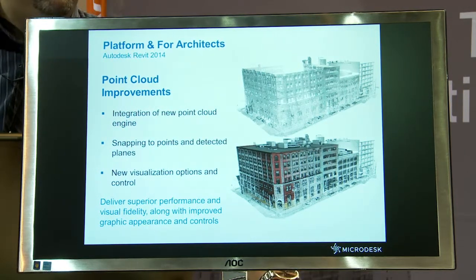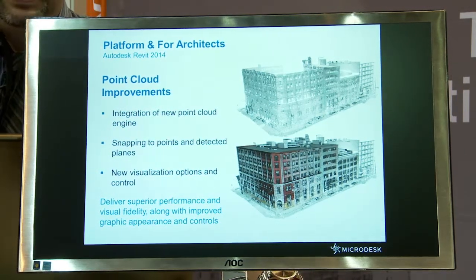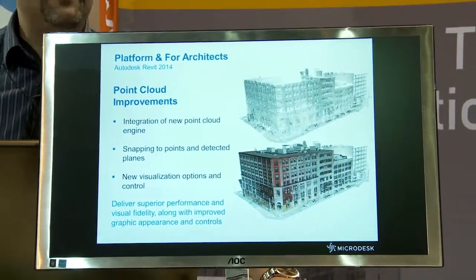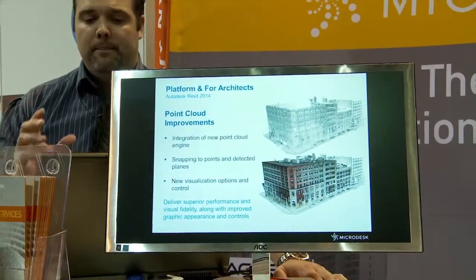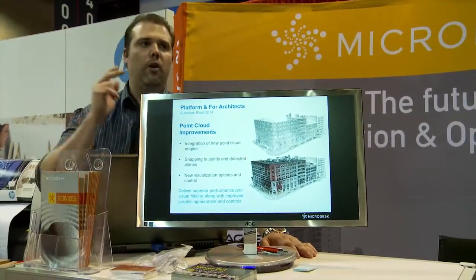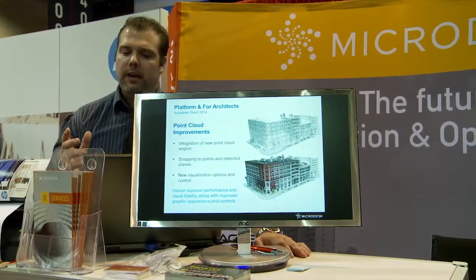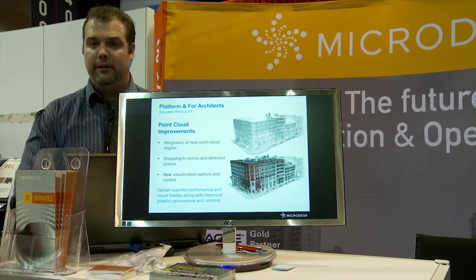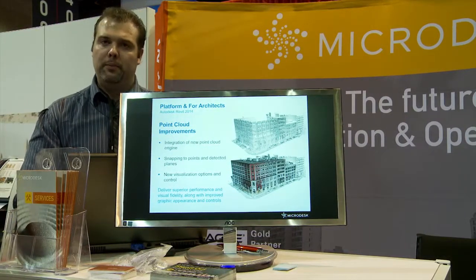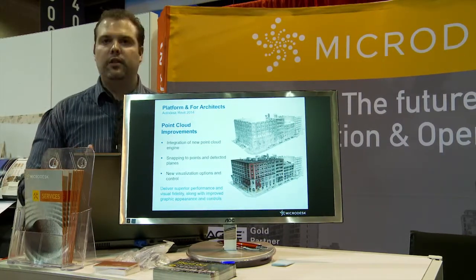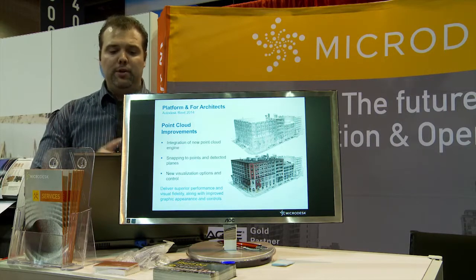And of course, you've heard about existing conditions. The biggest problem with Revit and point cloud files, which are those generated from laser scans, is first of all, there are about 50 manufacturers today that produce laser scan information. Whichever you use, like Faro or Trimble, the problem was that you had to use their custom software to even utilize it in Revit, or you had to buy some kind of plugin that would allow you to bring that file in. And it would be so heavy that later on you wouldn't use it for anything other than seeing it in the background. Now you're able to use Recap.